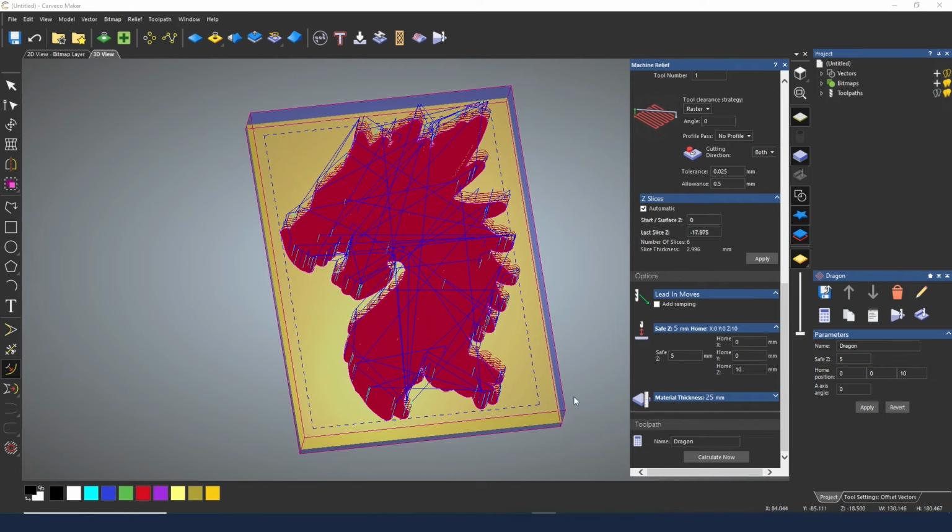So those are all our toolpaths generated, and you can see what we were referencing earlier in terms of within the vector or the whole relief. Because we selected to just do toolpaths within our vector, this is the area we were working with. But if we'd have selected the whole relief, it would have done toolpaths for all of this dead space around the outside.